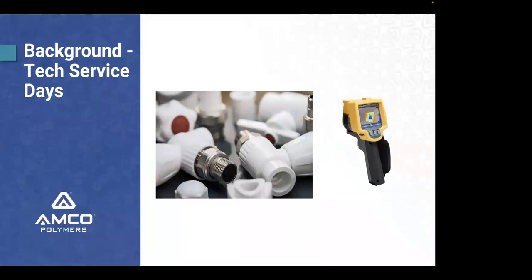They have 1/2 inch and 3/8 and quarter and female and male and different interactions. And I said, okay, what kind of cycle time can we run? I said, well, it depends on which combination of tool we have, how many inserts we have, and the wall thickness. So I said, all right, I'm going to use my infrared camera and find the hottest parts, and we're going to link my cycle time to the hottest part of my thickest section.